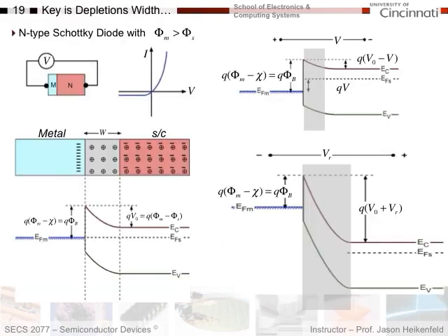So what I want to do then is modulate the reverse-biased depletion region of a Schottky contact and use that as my gate. And again, here I am with positive voltage. I don't want to do it that way because with positive voltage I start to get a ton of current spilling over from the N-type side into the metal, which has positive voltage. What we're going to do is instead put negative voltage on the metal, which is going to increase our depletion region width.